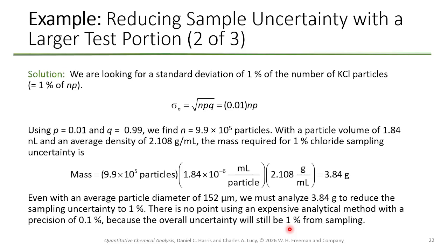And this is why, for example, you'll often see that Pace Analytical or any other analytical company or program doesn't just run everything on $500,000 to $1 million instruments that have 0.1% or 0.01% uncertainty on everything, right? Because if your sampling error is around 1%, then running it at 0.01% for the analytical error isn't worth any additional cost. You don't gain anything, right?